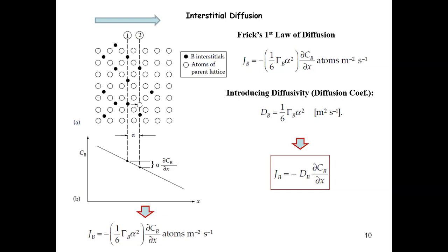Again, I assume that you have already seen at least Fick's first law of diffusion, but in a completely different context, like in liquid diffusion. But here, we derive this for solid state diffusion. For different systems, as long as the system is diffusive, the flux of that particular diffusing atom is always going to be proportional to the minus of the concentration gradient. The constant of proportionality is also called diffusivity, but the physics contained in diffusivity is quite different.